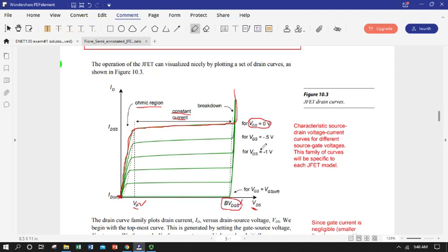Okay, so this plateau that we've now defined under conditions of no gate throttling defines another spec characteristic, and that's I drain to source steady state, or saturated. That's the most current you're going to want to ask that device to give you on a steady basis. So that's another kind of operating limit of the device.